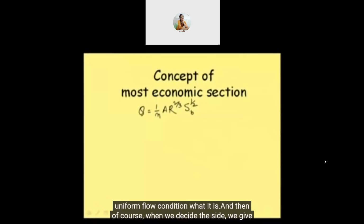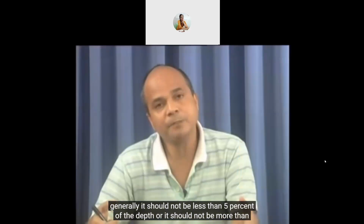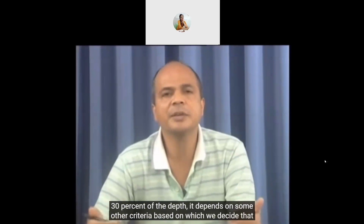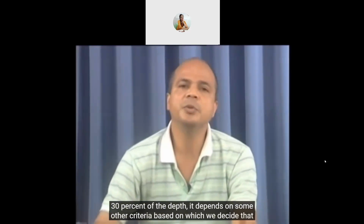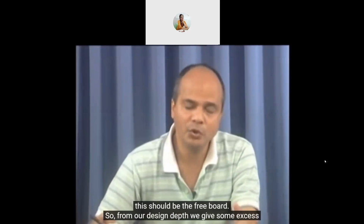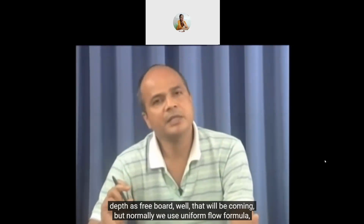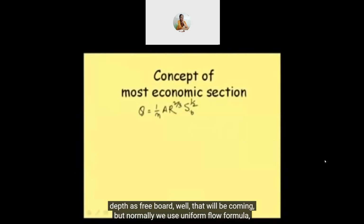And then of course, when we decide the section, we give some excess height, that is called freeboard of the canal. That freeboard generally should not be less than 5% of the depth, or more than 30% of the depth. It depends on some other criteria based on which we decide the freeboard. So from our design depth, we give some excess depth as freeboard. Well, that will be coming, but normally we use the uniform flow formula.